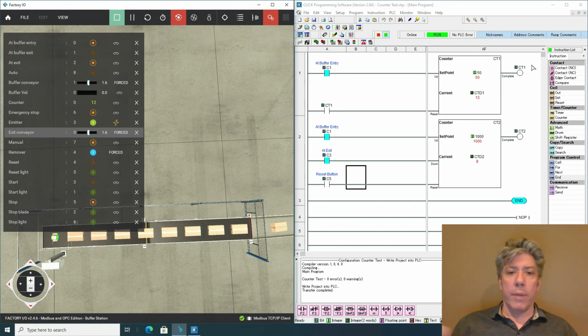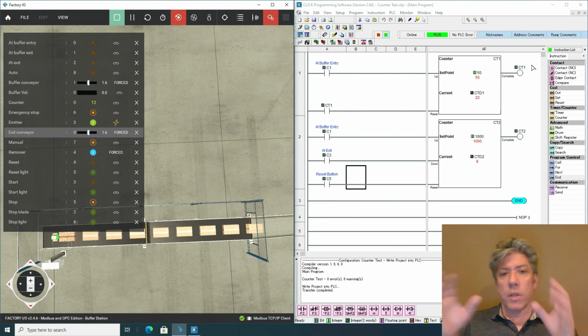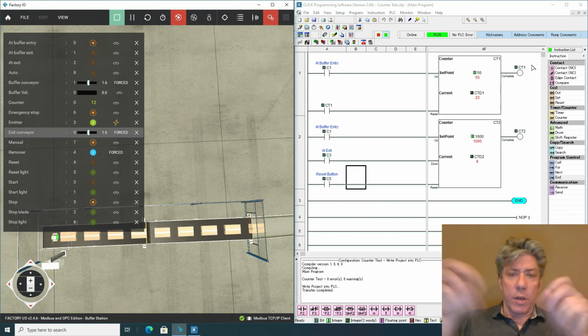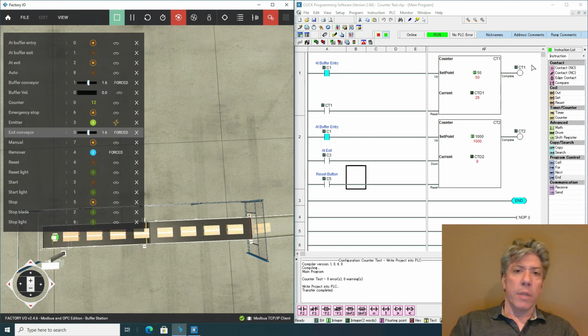And of course that bit can trigger other things to happen. Maybe you're palletizing something. You've got a pallet and you're putting boxes on it. You need to count how many boxes are going onto that pallet. I believe there's even a simulator like that in this program of Factory I/O. And so you need to count how many boxes you're putting on a pallet. Well, a counter is perfect for that because your PLC program is in control of the system, and it knows, if you will, when it has put a box onto the pallet, and so it can simply increment the count when that happens.